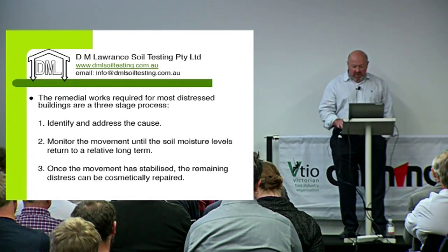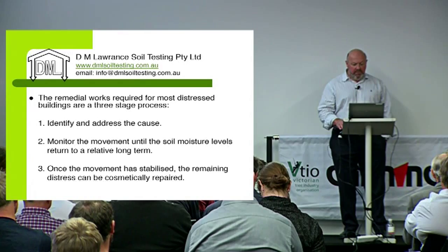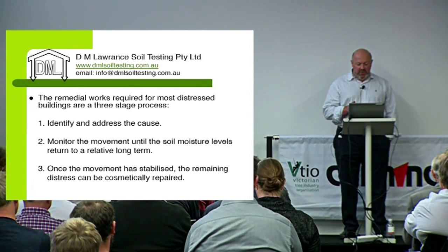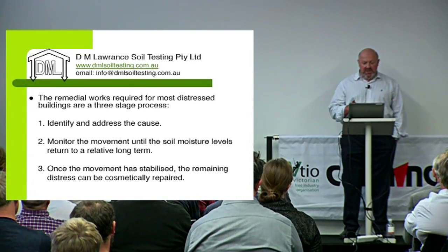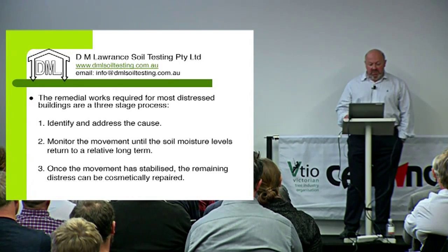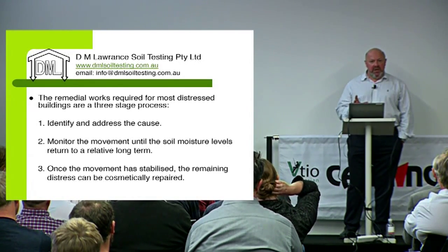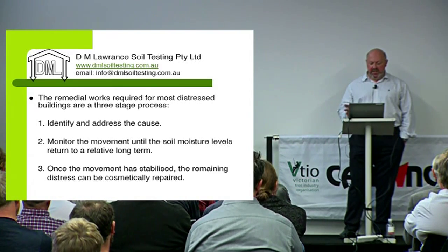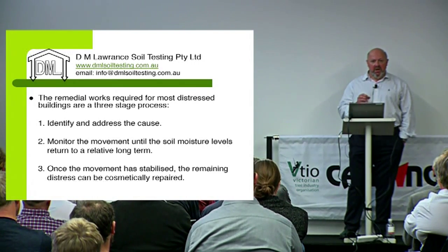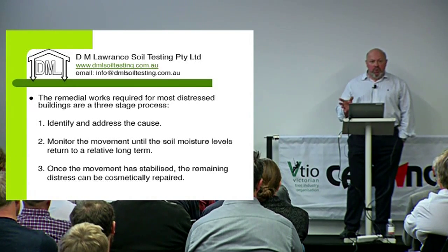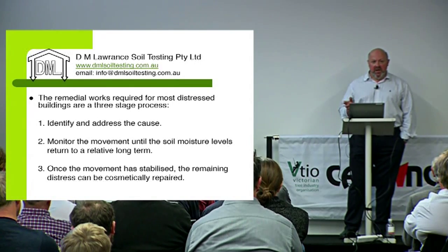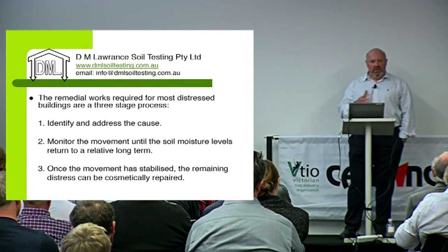We've had some clients recently where it's been determined that the cause was significant trees. The cracking was not that bad. Once they're armed with the information that the cracking is not going to get a lot worse, because if the clay is close to its maximum dry potential, the potential for it to go much further is not that bad, they value the tree much more highly than they worry about the cracks. So once they're informed what the cause is, they do nothing. And that's completely okay as well.